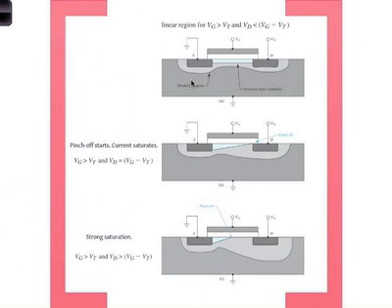So what happens for the device which makes it switch between these different regimes? For the cutoff regime it is easy to understand because the two PN junctions are reverse biased, so it's trivial. There's nothing there. For the linear regime, what happens? We said that the gate voltage is beyond some threshold. What does that threshold mean?